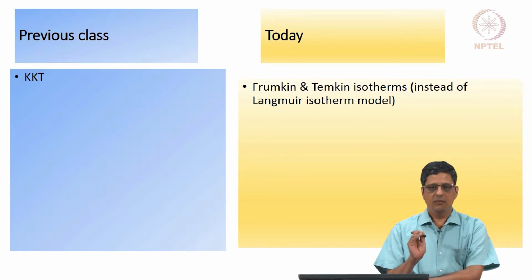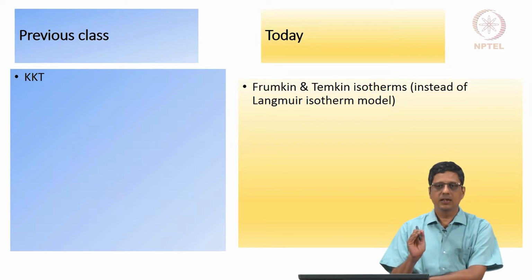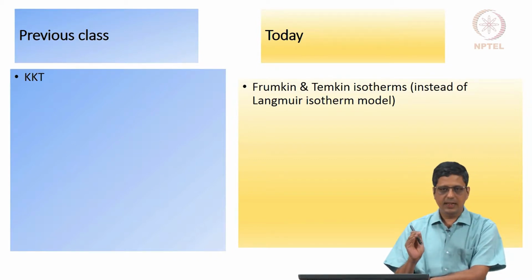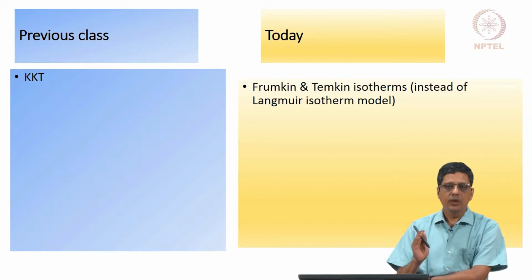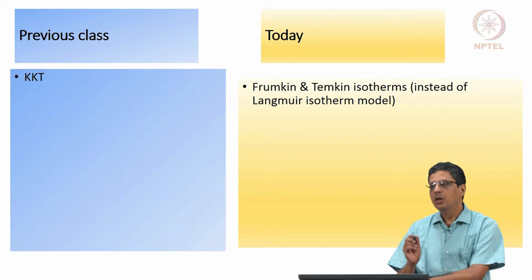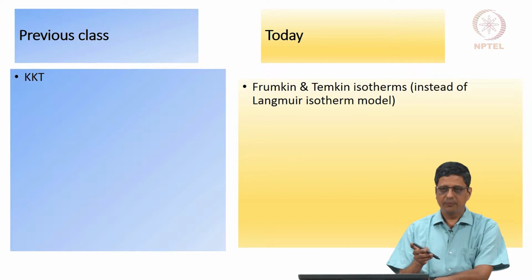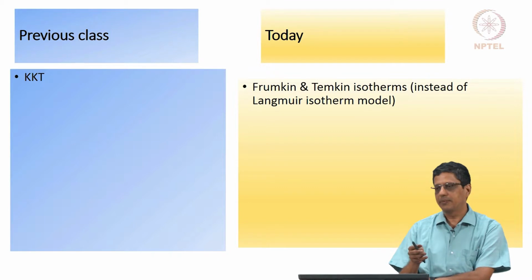So far we have said whenever there is an adsorption involved, the Langmuir isotherm model is applicable. The main reason we have done that is so that we can get an analytical expression. When we expand the expressions in Taylor series and truncate after the first term, we could do all this easily when the Langmuir adsorption isotherm model is used. But there are other models which might be more appropriate. They are a little more complex, but if you want an analytical solution, it is not easy, and in some cases it is not possible to get analytical solutions.